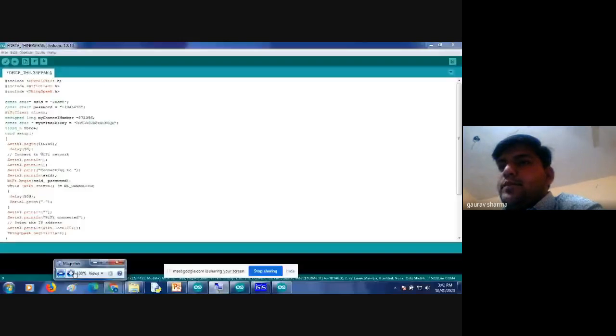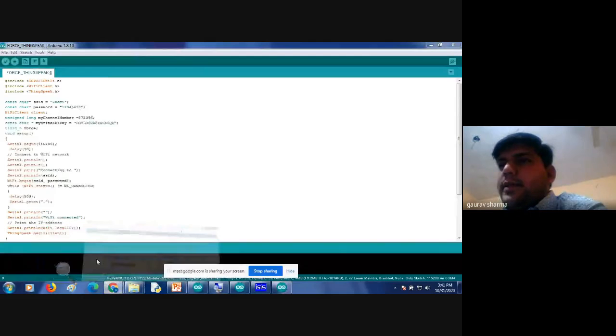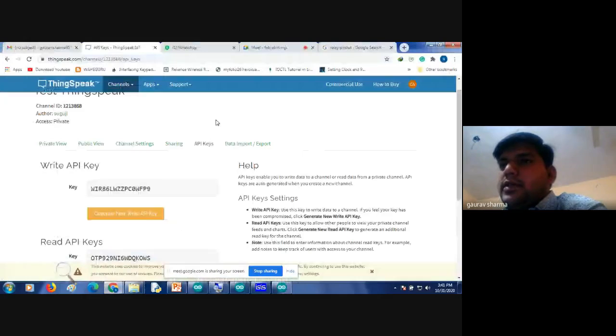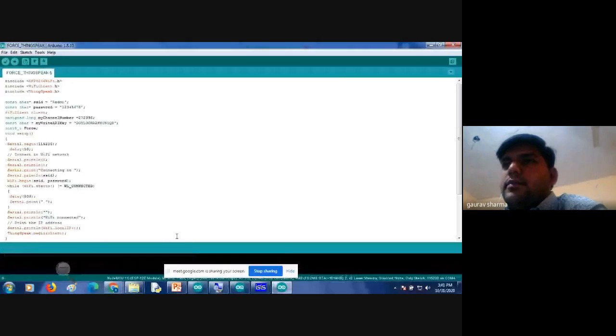Let me take you to ThingSpeak. What we need is a channel number and the API key. Let us take this write API key, copy it and paste it into this place. Another thing is there should be a channel number here.